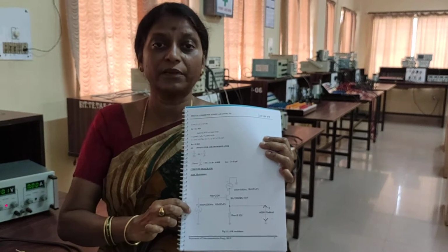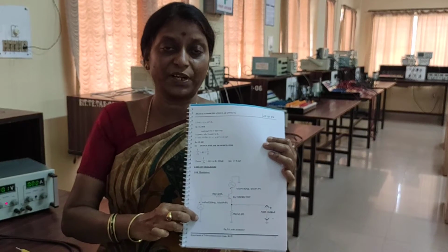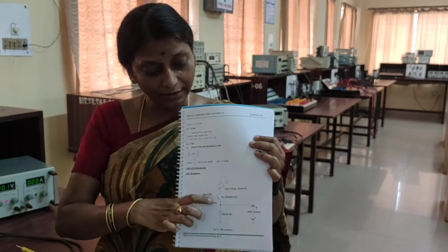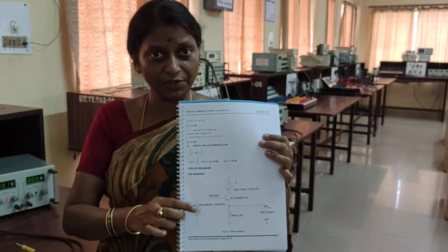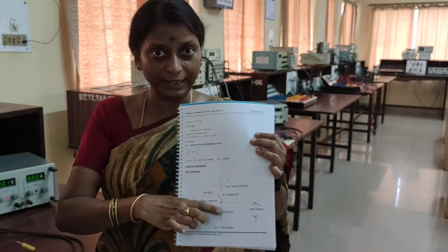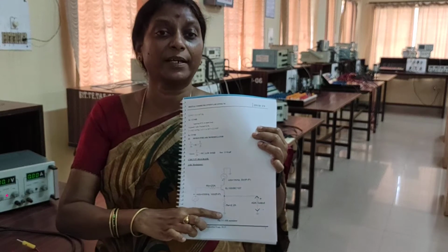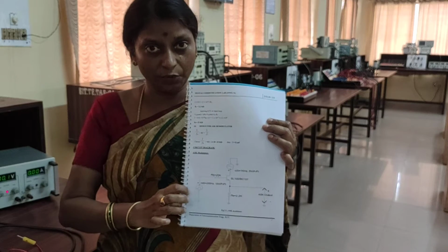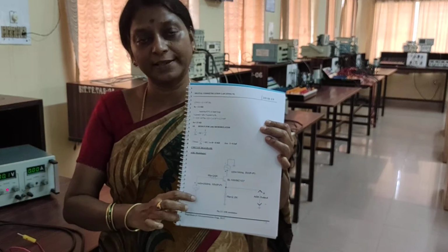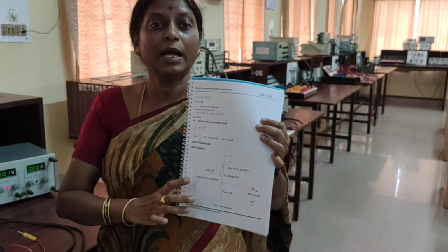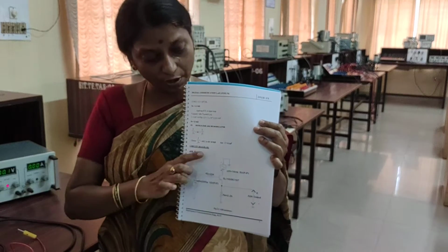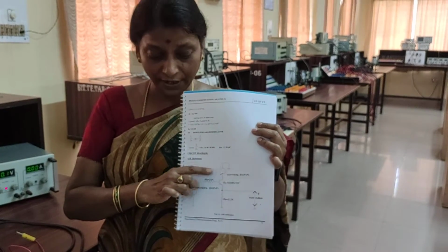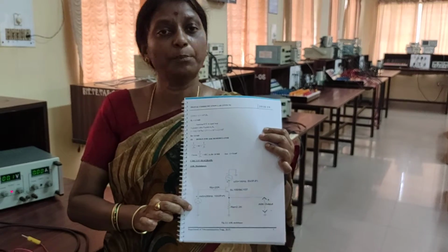Once the binary signal goes negative, to -5 volts or binary 0, the transistor will be in the switched off condition. When the transistor is off, the current is 0, so no signal will appear at the output of the emitter. So depending on whether the signal is 1 or 0, you will get the ASK signal, amplitude shift keying: the amplitude of the carrier is shifted according to the modulating binary signal.